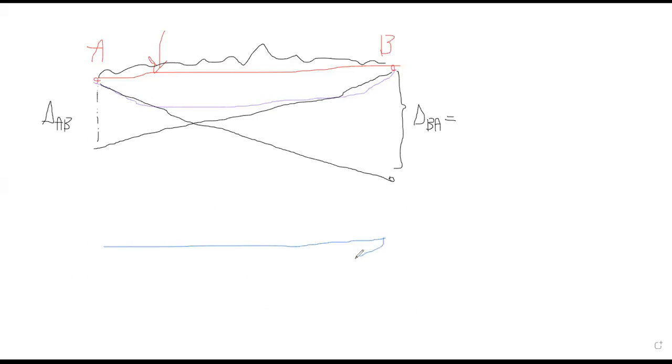So let's hope this is your bending moment diagram. The first point tells you where you need to take the moment of area. Here you should take the moment of area from A, and here you should take the moment of area from B. So it's between A and B, and you need the total area. The total area is the same for both.